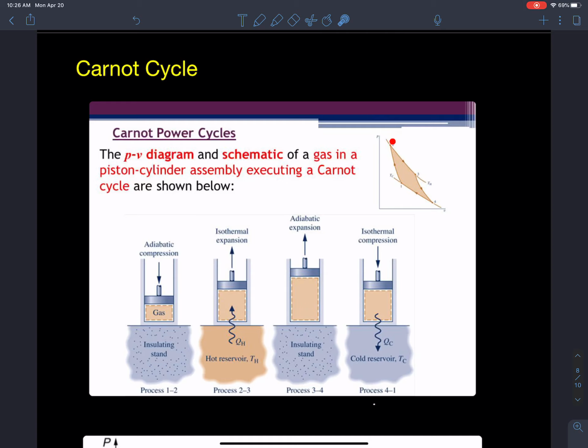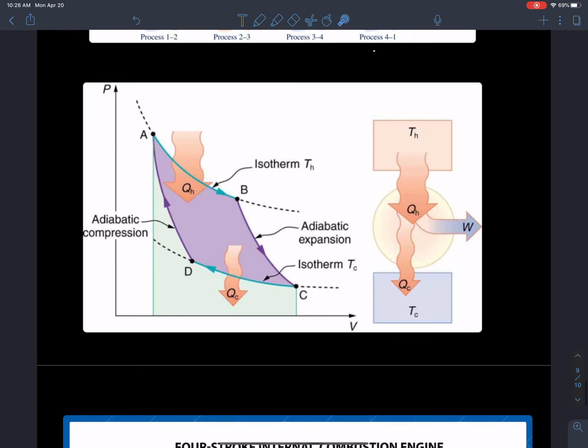And we have to be able to calculate the energy in that Carnot cycle in a couple different ways. So here's just another description of what's happening. Okay, heat is flowing in that isotherm. We had that adiabatic compression and heat flowing in. And then we have the adiabatic expansion and then heat coming out, being vented or going to the cold sink. And then the difference in that heat, the heat coming in minus the heat coming out, really gives us an idea about the amount of work that we're going to be doing in our system. Okay, that's a classic Carnot heat engine expression.